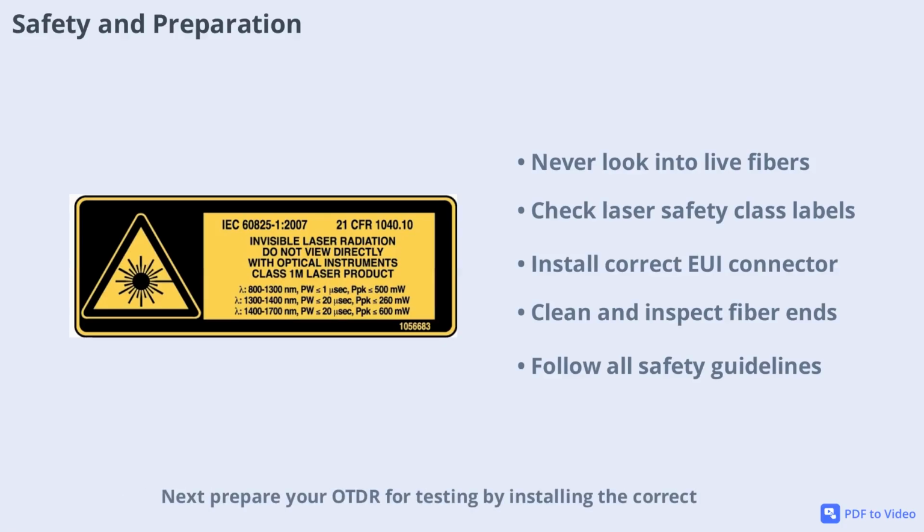Next, prepare your OTDR for testing by installing the correct EXFO Universal Interface (EUI) for your connector type, APC or UPC. Clean all fiber ends thoroughly using lint-free swabs and isopropyl alcohol, then inspect them with a fiber inspection microscope. Proper cleaning and handling prevent measurement errors and equipment damage. Once everything is clean and connected, you're ready to configure your OTDR for accurate testing.